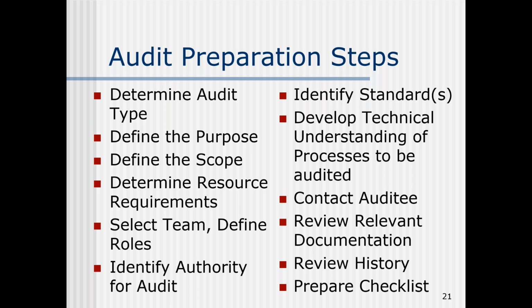Determining resource requirements, identifying the roles and responsibilities if there's going to be teams. Otherwise, the auditor develops the schedule, communicates, makes sure that whoever is doing the audit has a technical understanding of the processes. That individual does not have to be an experienced welder to audit the weld activity, but they need to understand the mechanics of welding to know, is the process being followed correctly or incorrectly?